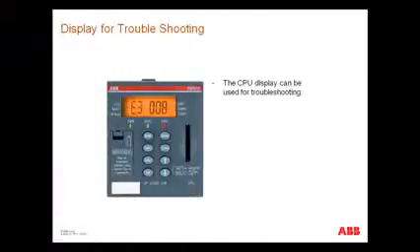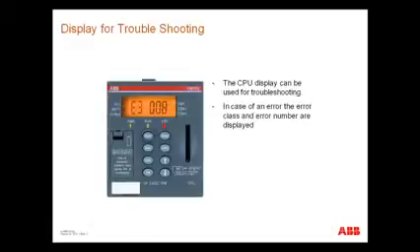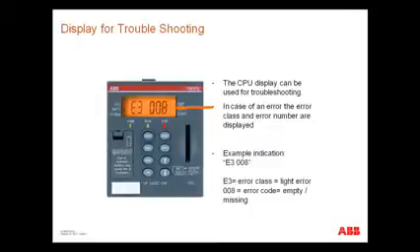The controller display can be used for troubleshooting. In case of an error, the error class and error number are displayed. In this example E3 indicates a light error. The number 8 is indicating that one component is missing.